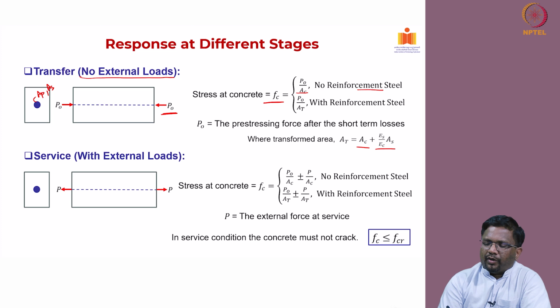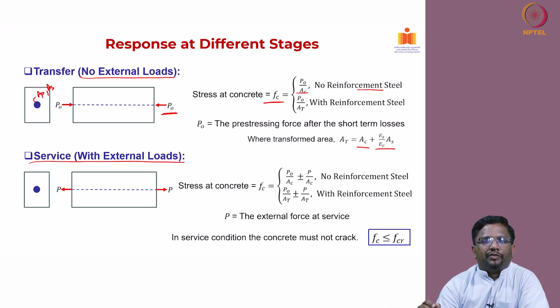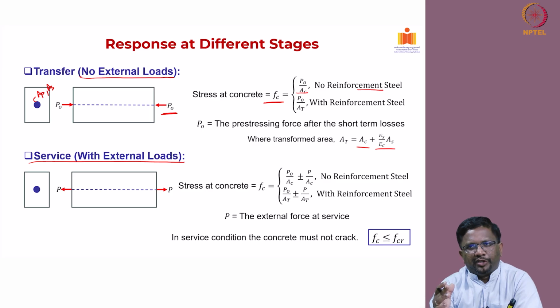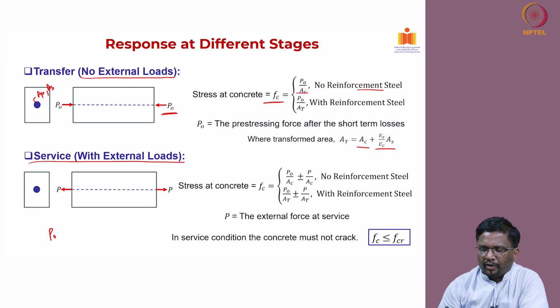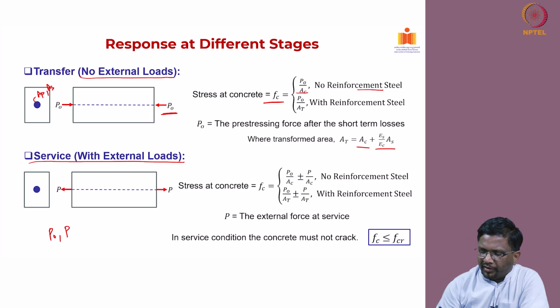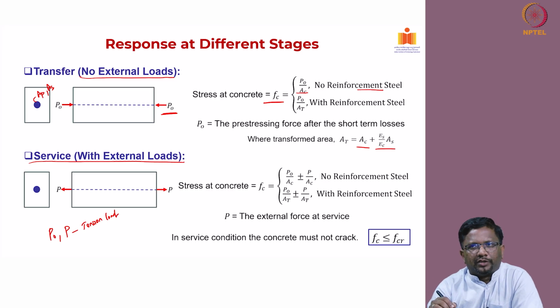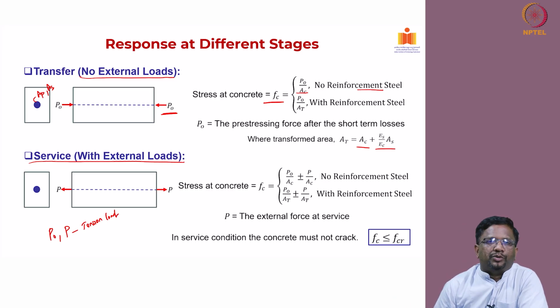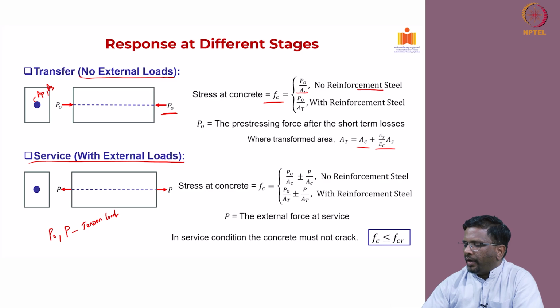Now, we can also calculate the stresses under service with the external loads. Now, see, in a pre-stress element, you have already done the pre-stress with P0, okay. In addition to that, you are also subjecting an external load P, in this case it is a tension load, okay, it is a tension load. Then how do I calculate these stresses? It is very simple, you can use the principle of superposition, and P0 by AC is the initial stress due to pre-stress.